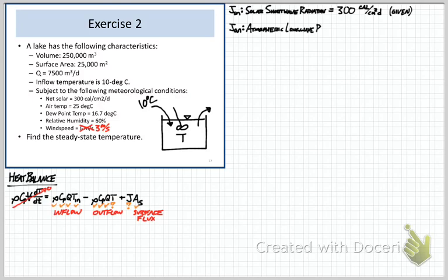The next flux that we'll think about is atmospheric long wave radiation, sometimes called black body radiation. This is radiation of heat by things that have heat, and so we're thinking about our Stefan-Boltzmann law. In addition to that, we're correcting for two things. One is atmospheric attenuation, the middle term that I've shown, and the second is reflection. From class, you'll remember that we've got an attenuation constant of about 0.6. We can estimate that about 3% of that radiation is actually reflected rather than absorbed.